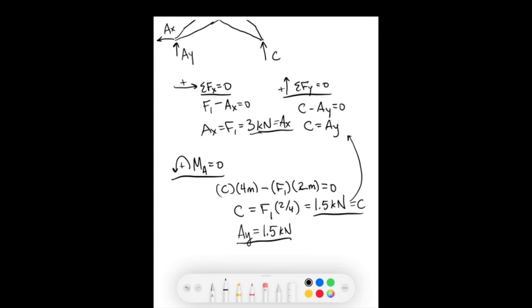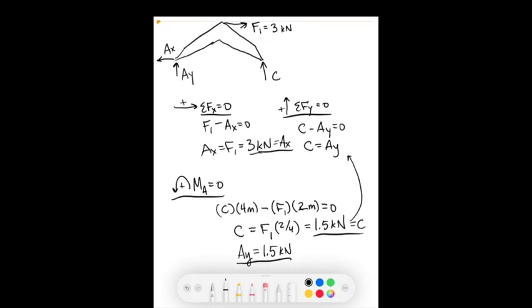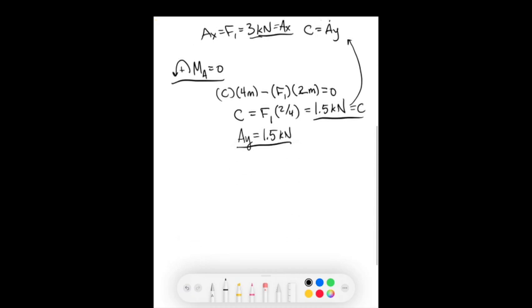So first thing we'll do is we'll start at the best point. The best point is probably at point C, since there's a simple one force direct reaction at point C. So we'll start by drawing joint C, and we have the reaction C. And I'll assume that the force in member BC is acting in compression, and the force in member DC is acting in tension. If our assumptions are wrong, it's okay, it'll just be a negative answer. We'll still get the right answer.